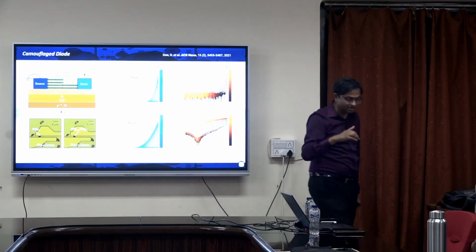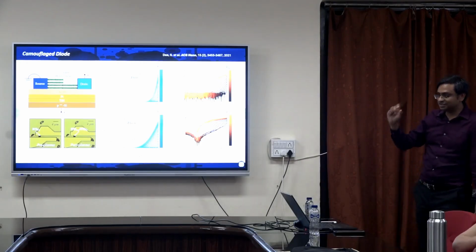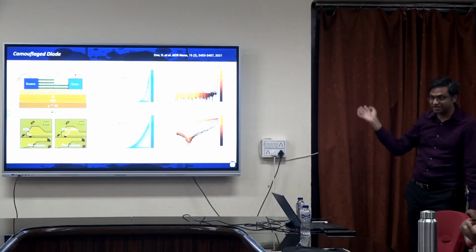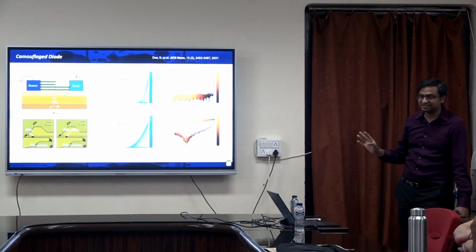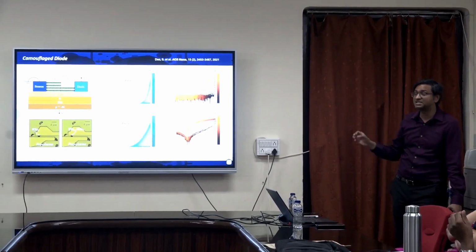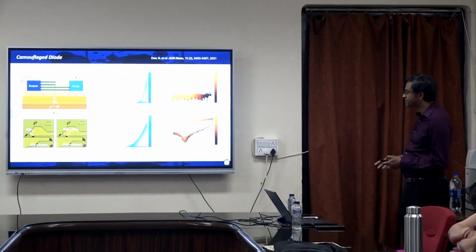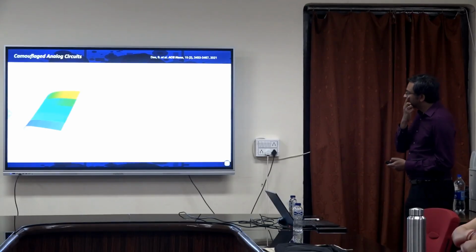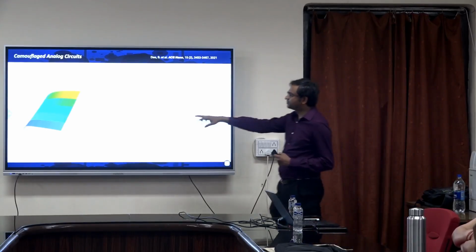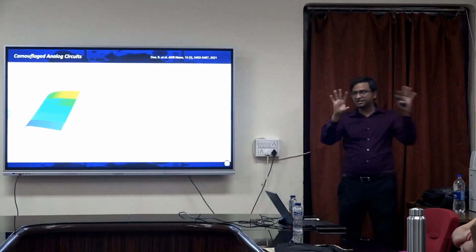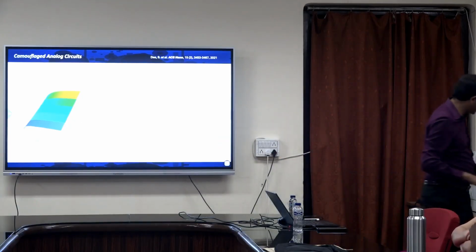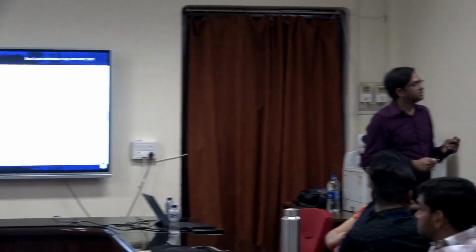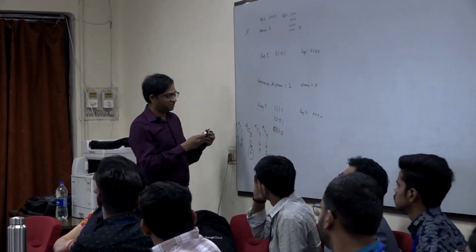So not only can I make the same device as a resistor, as a diode, as a transistor, I could also make diodes with different turn-on voltages, and resistors with different resistance values. So I get enormous flexibility in designing circuits and camouflaging their functionality. Okay, I will come to the camouflaging, and these are the transistor characteristics which you have seen. So now you see the number of trials, because for example, if I make a circuit, let me draw it over here. So let's say there is a circuit over here, I will just draw it on this.